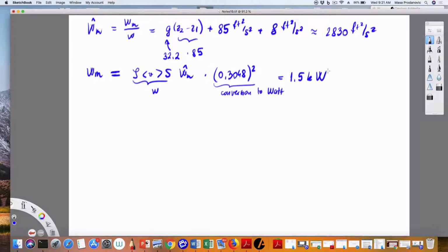So the biggest deal is to approximate the Reynolds number so you know the flow regime, and that determines which values you're using in estimating friction losses. That's what it comes down to. Or which formula for that matter. Because for different formulas, we have different fits to the data. Other than that, it's relatively straightforward.